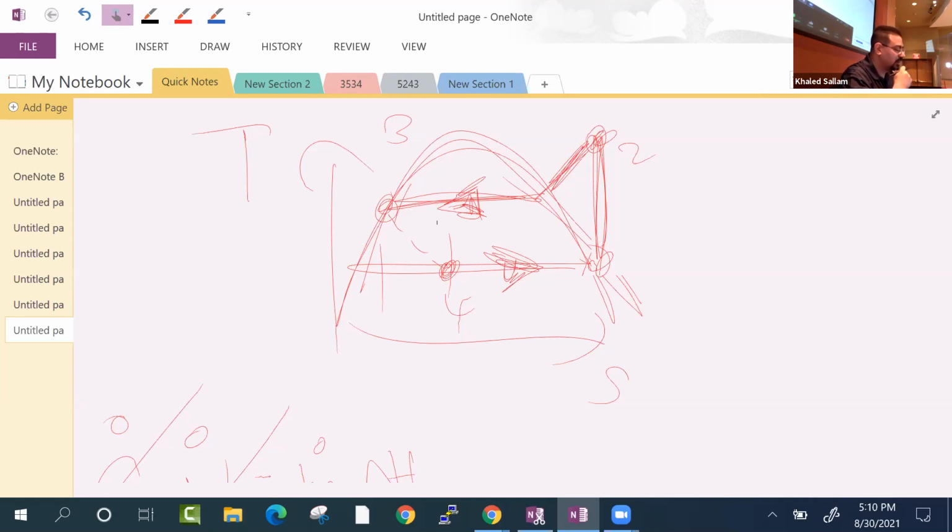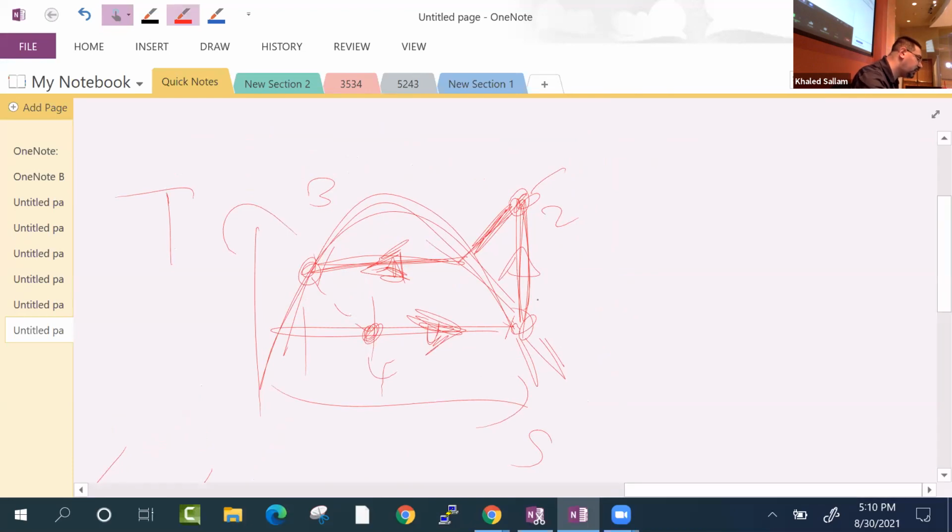Yes. This is assuming ideal what? Ideal. Yeah, well, ideally it's isentropic, but in real life it will go a little bit to the right. Yes. So this is 2s and this is the real 2.